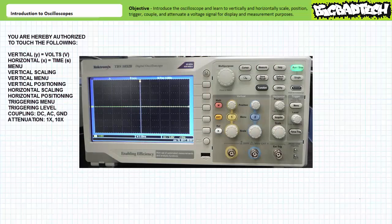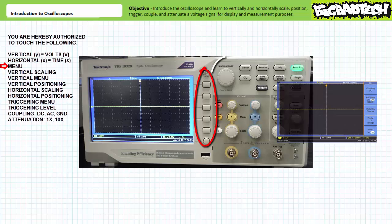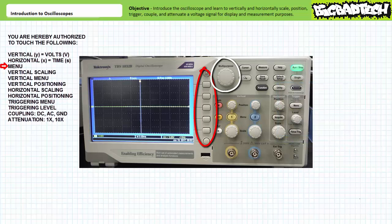Alright, this about wraps up our brief introduction to the oscilloscope. Since we introduced a lot of different important concepts in a short time span, let's do a quick review and discuss common oscilloscope troubleshooting events before we say goodbye. The screen displays voltage on the vertical y-axis and time on the horizontal x-axis. The screen also displays menu-specific items, and items within a menu can be selected using the buttons on the side of the screen, as well as the multi-purpose knob in the operations group.